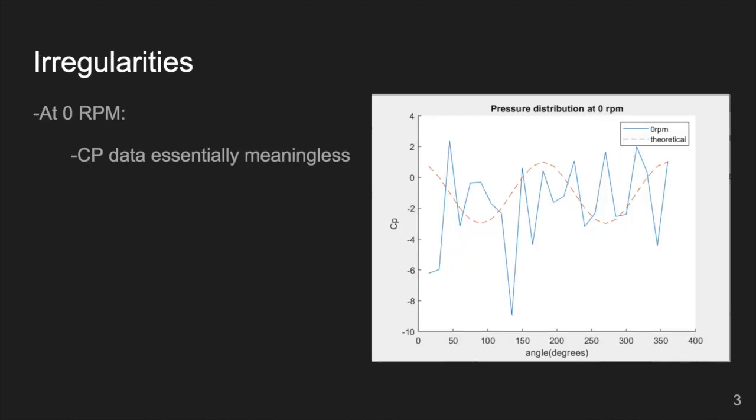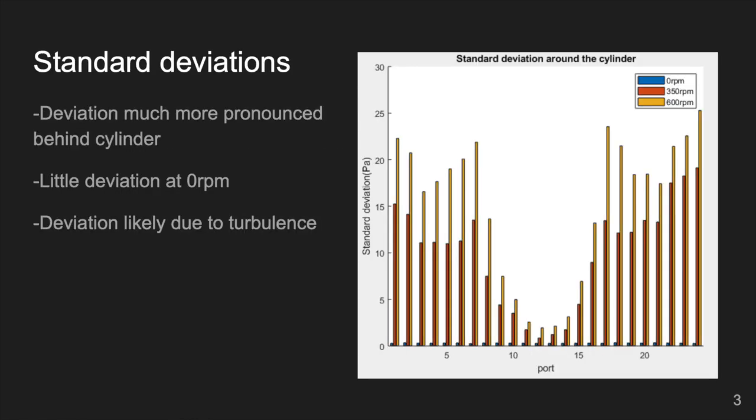The pressure coefficients gathered when running the wind tunnel at 0 RPM have very little meaning to them. Since the pressure coefficient is defined by the difference between the static and dynamic pressure, which are both roughly the same when there's no wind speed, all of these numbers carry basically 0 information. This excuses the ones which are well above 1, as again, they are meaningless.